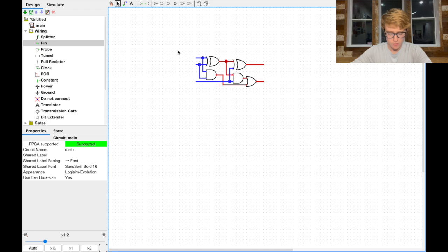So now we can move forward with actually solving this problem. So the first thing we need to decide is how many bits we want our output to be. And this is going to basically determine the max output value, the max number that we can count to. So I'm going to keep this simple and say that the number of bits we'll have is 3. So now if we have a 3-bit number, what is the max number? Well, it's 7, because the max would be 111, and 111 in binary is 7 in decimal. So the max we'll be able to count to is 7.